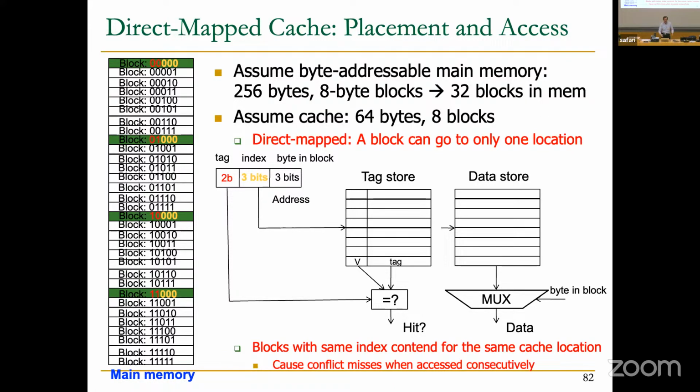There is a predetermined set of blocks that can be stored in index 001, and you know what those are. Those blocks with index bits corresponding to 001, right? Essentially, the blocks that are following these green blocks, and there are 4 of them. Okay? Any questions? So once you understood this, you now actually can build this cache, right?